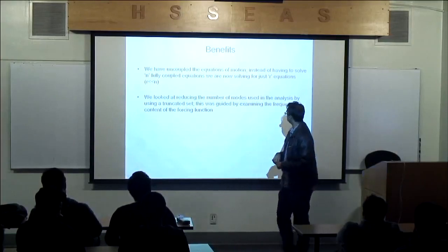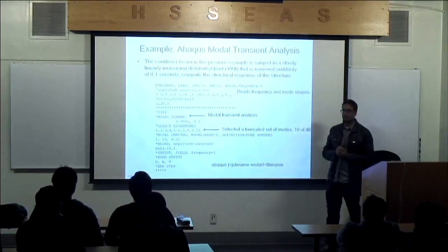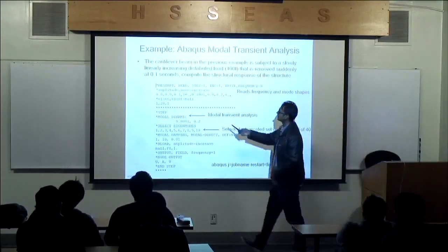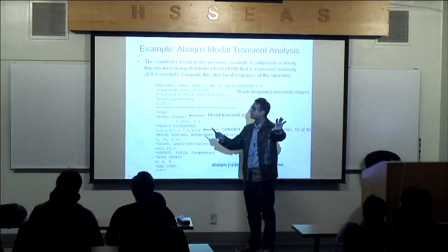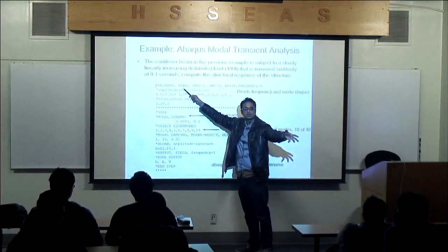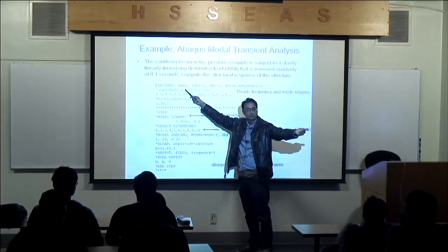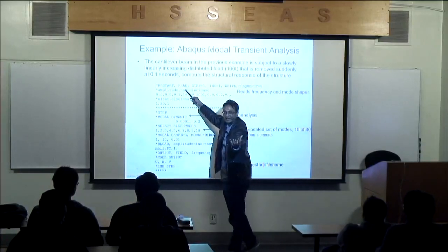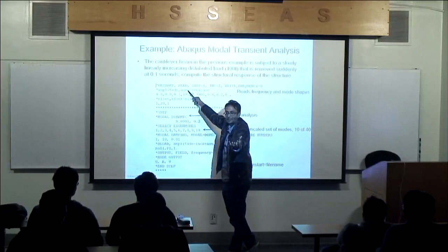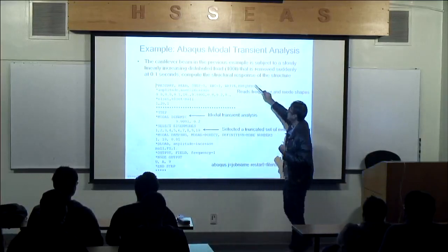All right, so how do we do this in Abaqus? In Abaqus, remember when I had a restart step, I was writing the solution to a file? I was writing the DNA. Remember that step in Abaqus earlier? Yes? So now I'm going to read that DNA. I'm telling Abaqus, I know the DNA of this structure, so please read it for me. That's what that step is doing. It's reading the information, the DNA.